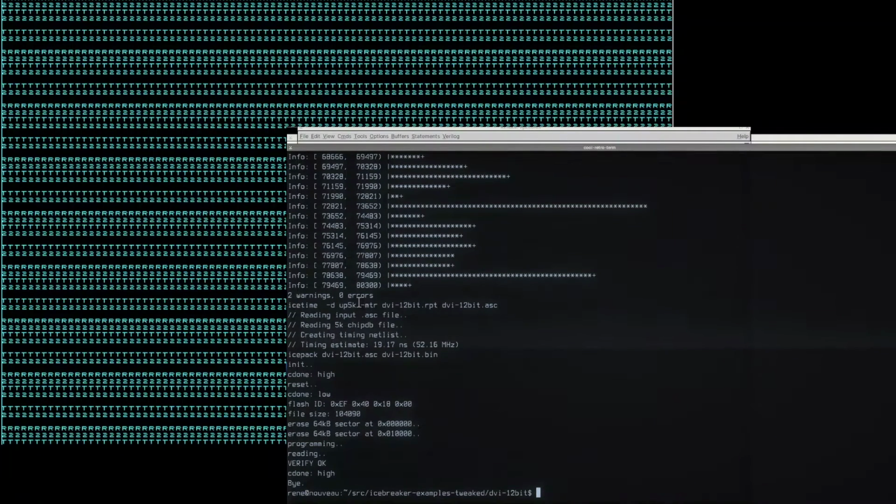And actually the edit compile time is not too bad. And also, if we would synthesize the whole Pico RISC-V core, this would on this Mac Mini, as you've seen in the previous live stream, take 10 minutes or so. That's certainly why you want to use an AMD EPYC, AMD Ryzen or some Threadripper, because then the synthesis time of Yosys is probably coming down from 10 minutes to 30 seconds or something of that sort.